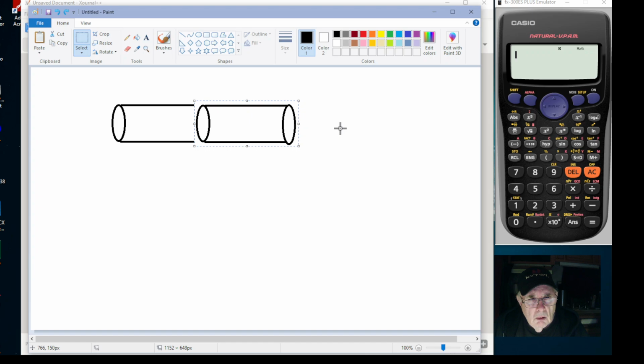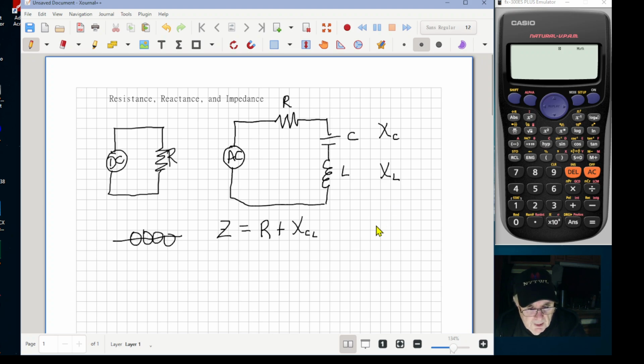So don't get that confused with the efficiency of an antenna system. We just don't want any opposition to the flow. Think of it this way: I could have maximum transfer of energy from the back end of my radio going into a coat hanger and have a perfect impedance match, but a coat hanger is probably not a very efficient antenna system. Whereas if I have a 4-element beam with high gain, I've got an efficient antenna for receiving as well as radiating energy. So that's the idea with impedance matching and why that's so important.